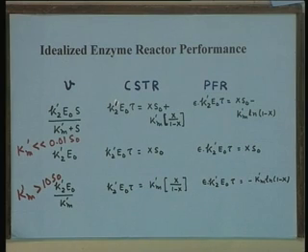So, relative decrease or increase of tau? Not tau, productivity, relative decrease of productivity. So, the effect of tau is more pronounced on productivity. Yeah, the effect of tau, no, the tau and productivity are inversely related, and therefore, if the tau increases with increase in fractional conversion more pronouncedly in the case of CSTR, the reverse will happen in the case of productivity.